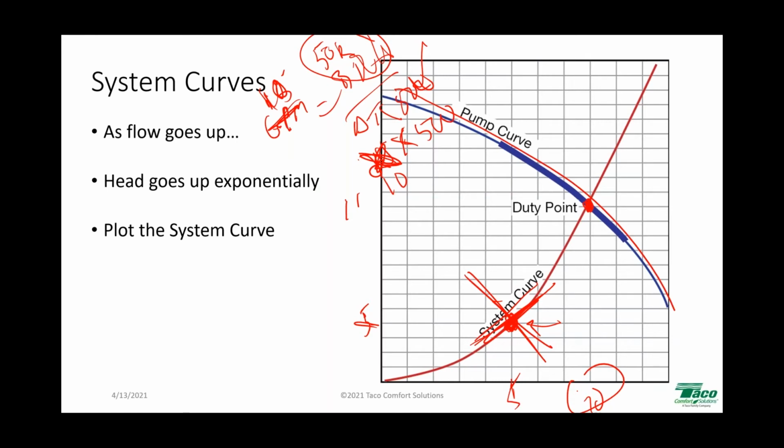That's not the problem. The problem is we are deliberately short cycling the boiler, which means whether it's a cast iron boiler or a mod con boiler, it's never going to be as efficient as it could or should be, ever. Number one. And number two, when we start short cycling, we're turning things on and off and on and off like that. Well, what do you think is going to happen to all of the moving parts? We're going to start wearing things out prematurely, and we're going to have premature, unexpected, and unwanted service calls to replace potentially fairly expensive pieces of equipment. Now, that to me sounds like a problem. But there's never an immediate problem like, oh, the system doesn't work, they're freezing to death, they're blaming me. No, it's a much longer term problem and potentially much more insidious.